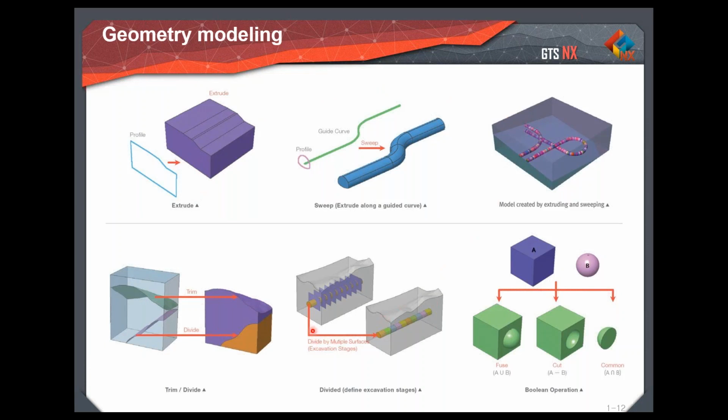So most of the AutoCAD commands have been incorporated in here. Let's say we have a tunnel which is changing its direction along the length. In order to model this particular condition, we need to have all the coordinates in X, Y, and Z, which will be very tedious for an engineer. What we can do in here is have a profile, that's your cross section, and then we have a guide curve. So this is my guide curve, which is representing the direction and length of my tunnel.